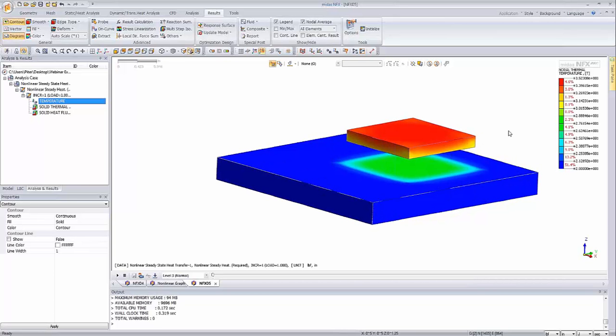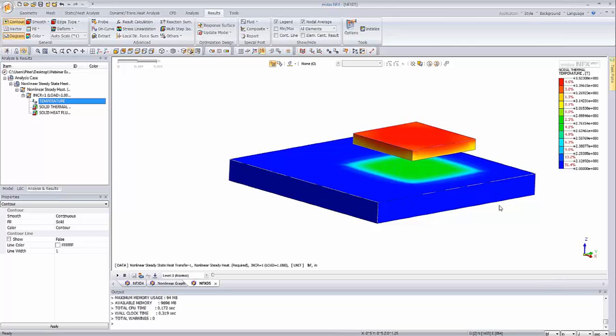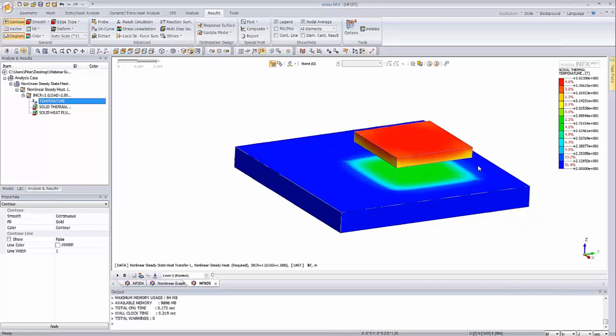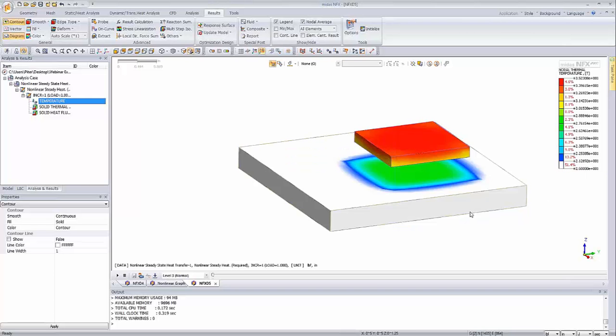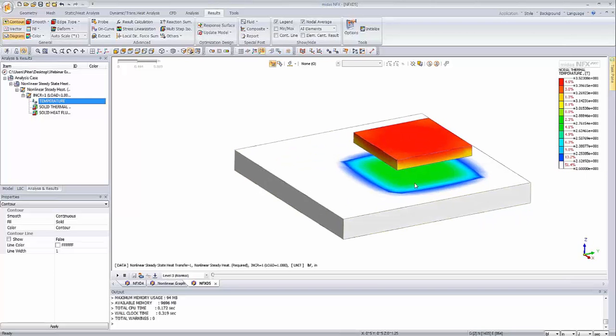And before we end this example, I would like to show you a trick according to the post-processing, especially to the legend. Maybe you don't know, but it's possible to change some parts of the legend. If you double-click on the color, you can change the color from the legend, and as you see, the model has been displayed in a different color.